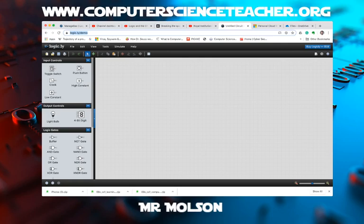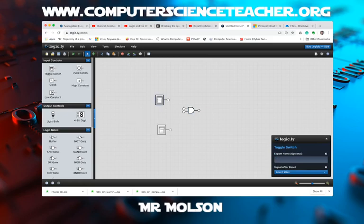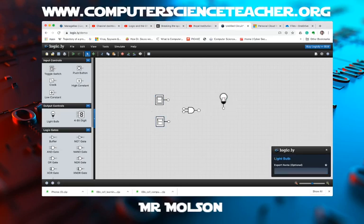Now we talked about the fact that most of the gates that we are learning about have two inputs. So here's our AND gate, for example. As you can see, here's input A, here's input B, and this is the output. So we're going to connect those two inputs to a couple of switches, which we've got here, a switch here and a switch here, which go there and there. Then, just so we can see the output, we're going to connect a light bulb to the output. So we're going to wire all this up, just like this, and we just connect it all together.